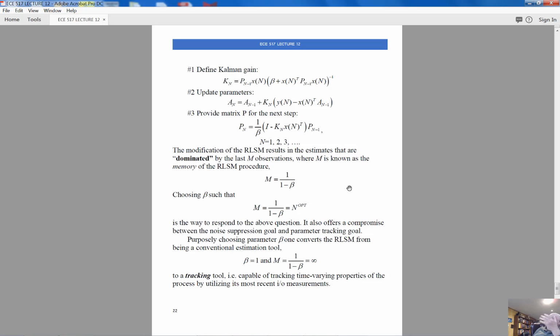So, if we use a forgetting factor, our estimation procedure turns into a tracking procedure when we follow changing parameters of the control plant. And I have to tell you this: if we have very small memory of the procedure, we will get the ability to track a very fast changing process. But the other side is that we will be losing the ability to reject noise. Our approach will not be quite a statistical approach. However, if we are interested in averaging out noise, then we have to have a greater memory of the procedure. But as memory becomes greater, we're losing the ability to track the process.